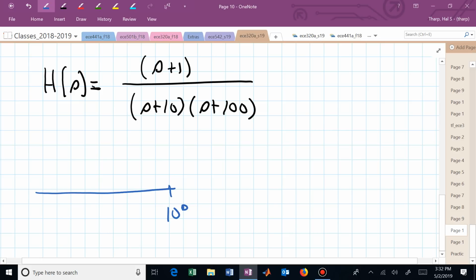That's 1. What's happening now relative to this transfer function's frequency response? We're looking at the magnitude of H in dB. What happens when we hit a zero's break frequency? What happens beyond that? Now we go up, don't we? 20 dB per decade.